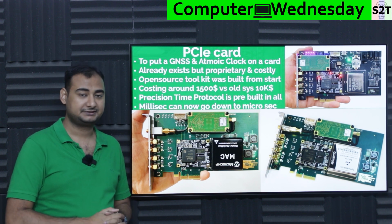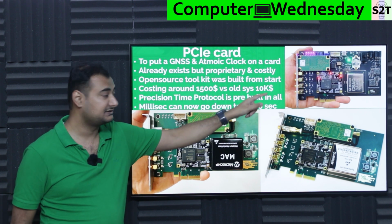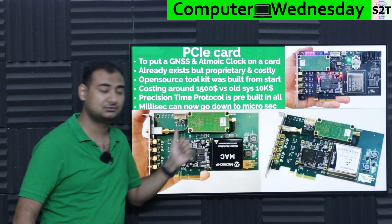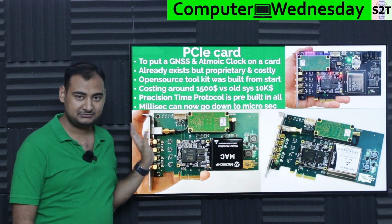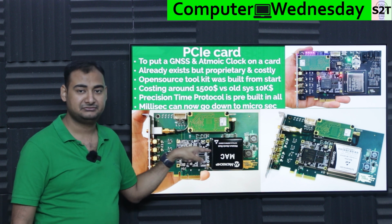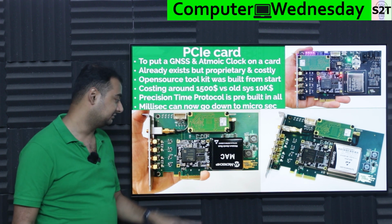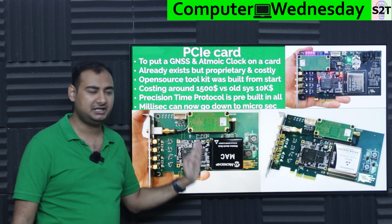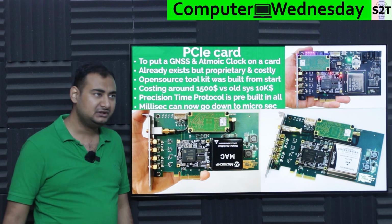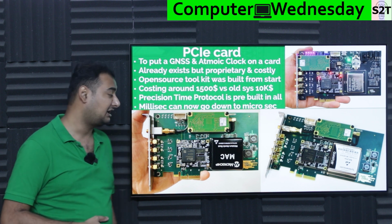So how do we solve it? Well, that's why you have to have an atomic clock. All these systems have a GPS receiver. This secondary card that you are seeing, that is the GPS receiver, and then GPS gives it the very precise time, and that time is synced with the atomic clock. Now, an atomic clock on its own has very low drift. These things are very precise, meaning they only drift by a nanosecond, not even a whole nanosecond in a day.